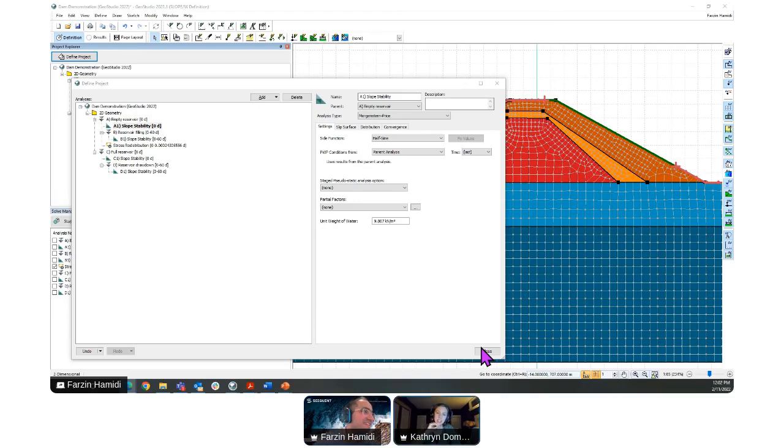I think so. Yeah, unfortunately there's not an easy way to compare results in GeoStudio to the results that you measure in the field. There's no way to overlay the GeoStudio results with field results. We don't have that capability yet. I'm not sure if that's something that will be coming. You'd have to export your results that you plot. For example, if you have vertical sections that you plot the pore water pressures along, bring them into an Excel spreadsheet and compare those to your data.